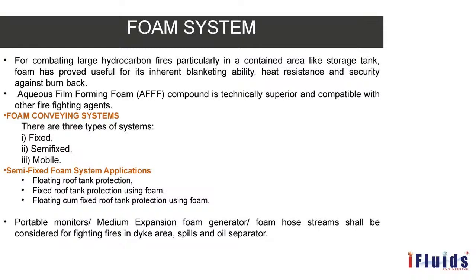Okay. So next we are moving on to the foam systems. For combating large hydrocarbon fire, foam systems are the most effective way of extinguishing. Especially aqueous film forming foam compound is typically superior when compared with the other foam compounds. There are three, four foam compounds described in OISD 116, which are detailed in the annexures.